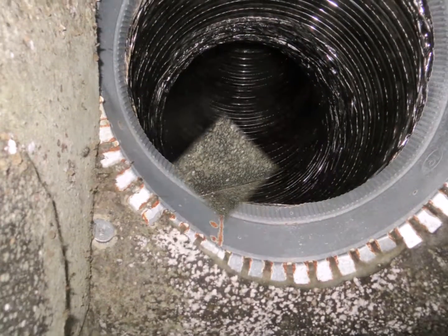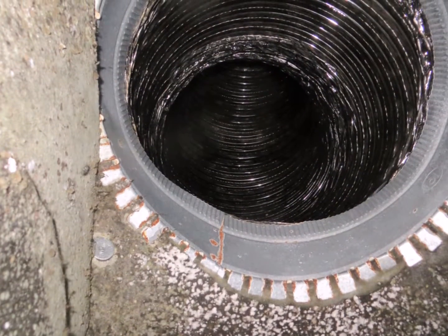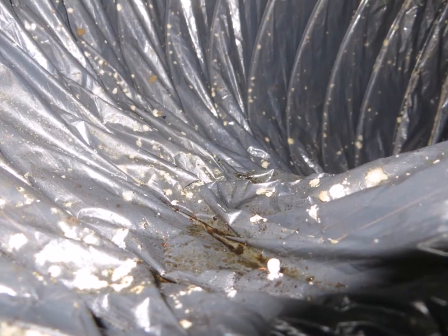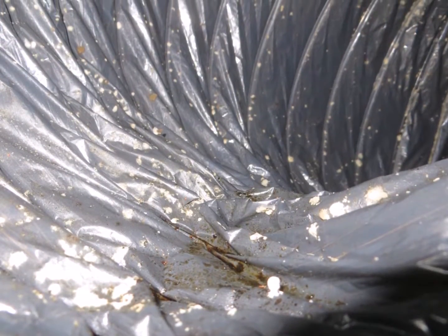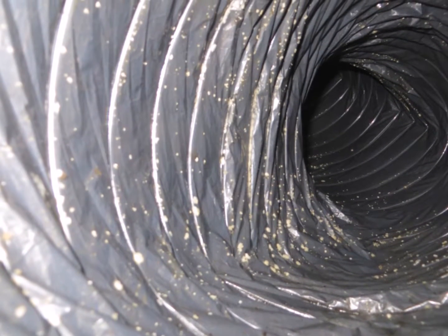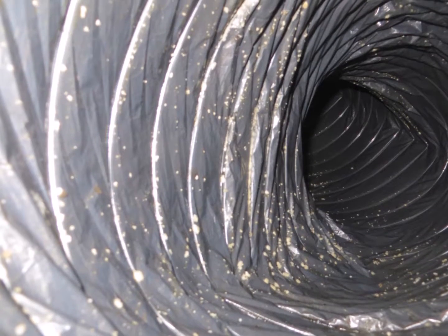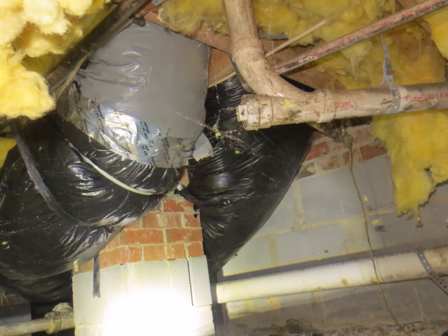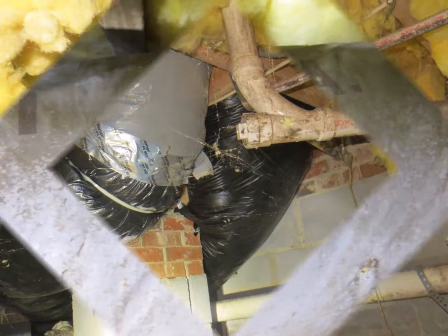This is an extensive amount of mold. Then there's a big duct that runs all the way upstairs, supplying conditioned air. This duct is the duct for the downstairs by the door, and you can see that it has mold in it, most likely Aspergillus penicillium. Here's the area where the vertical riser is, where the ducts run upstairs. There is mold growth on the outside of the ductwork in the crawl space.